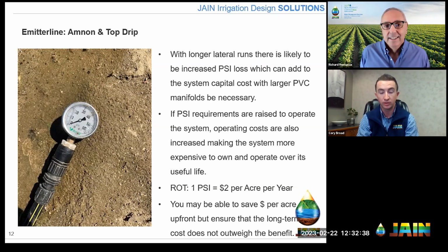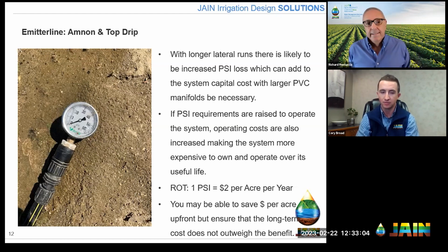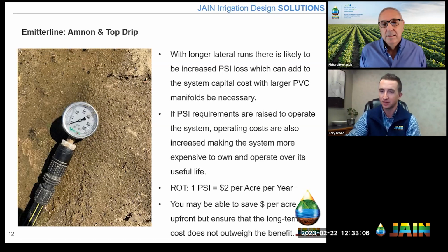you're going to be just fine. One thing I will say that's also important to consider is, yeah, the emitters are working fine while the irrigation system is on. But if you have a valley and then you have these low spots and you turn the irrigation system off, all the water that's been at the top is going to drain down to the bottom. And we see this a lot in the vineyard market in the coastal areas of California, where they would like to have what we call CNL technology, check non-leak or close non-leak, which effectively means that emitter shuts at 3.5 PSI and doesn't allow the water to drain out. So there'll be a little bit of drain down that goes on when you first turn it off, but instead of 100% of that line draining into the low area, it might only be 10% of it.